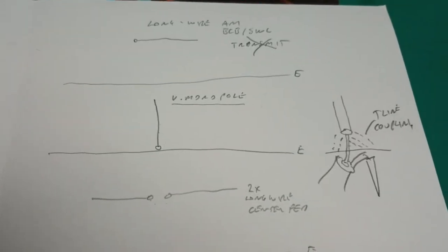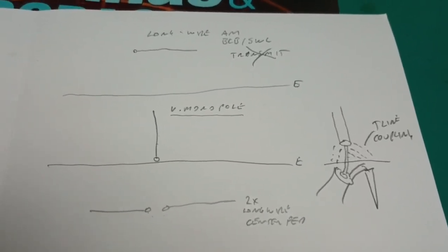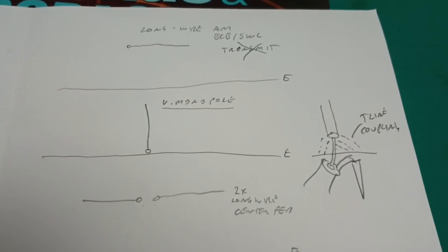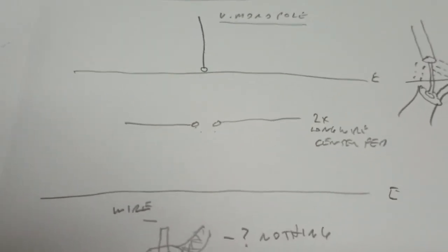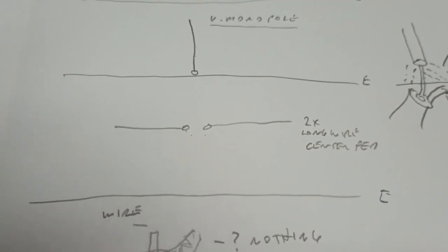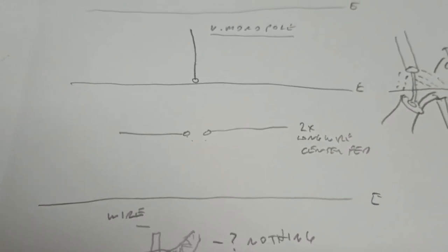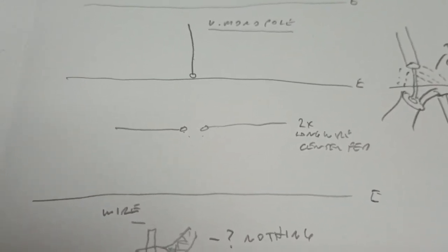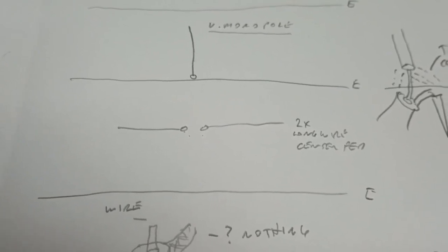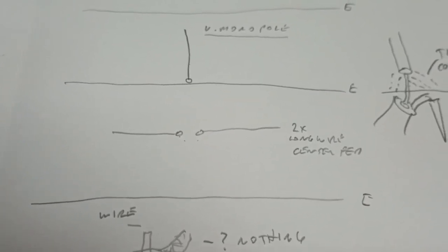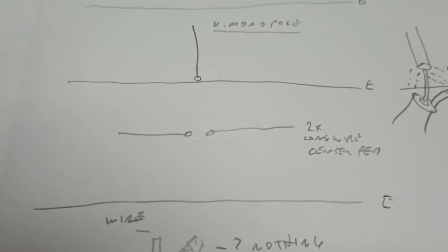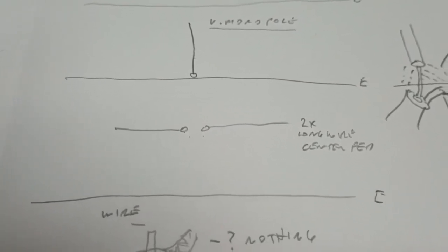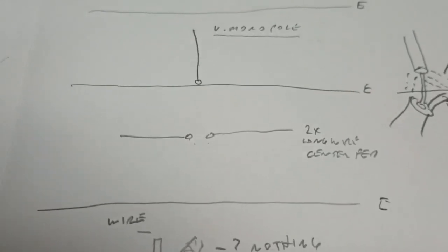And for bonus topic, did you know it's possible to have a correctly matched feed point and a high SWR? It is. I've proven to you in my antenna videos that the length of that dipole is critical to relate to the frequency, because the energy is traveling out the arms, being reflected, coming back, it's emitted in the process. That feed point can be correctly matched, but the wires be the wrong length, and there's still reflected energy.